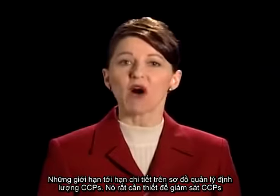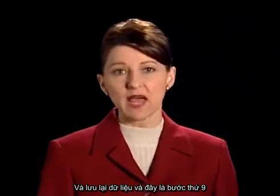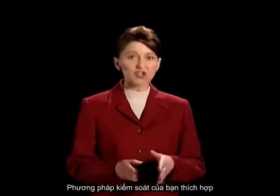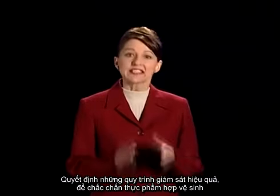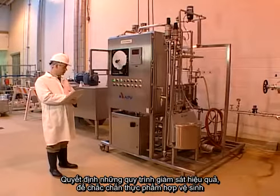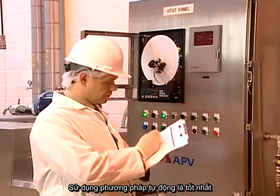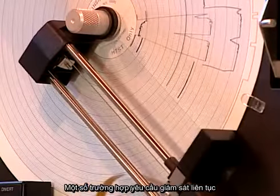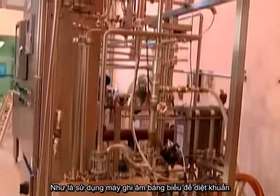It's vital to monitor your CCPs and record the data. And this is the 9th step to implementing HACCP. Monitor critical control points. Once your control measures are in place and food safety criteria have been established, decide on effective monitoring procedures. To ensure food safety, you must establish a monitoring schedule. Continuous monitoring using automated methods is best. Also, in some cases, regulations require continuous monitoring, such as using a chart recorder when pasteurizing milk.